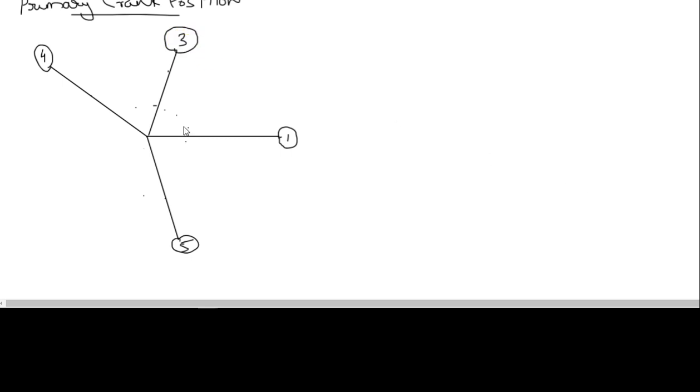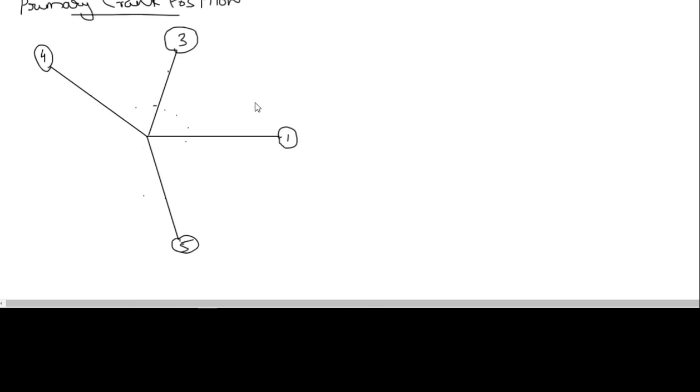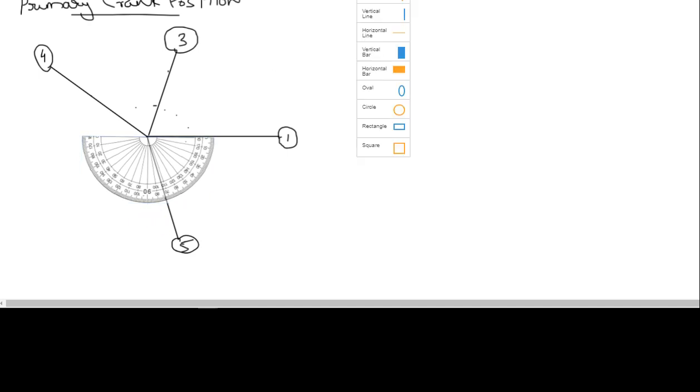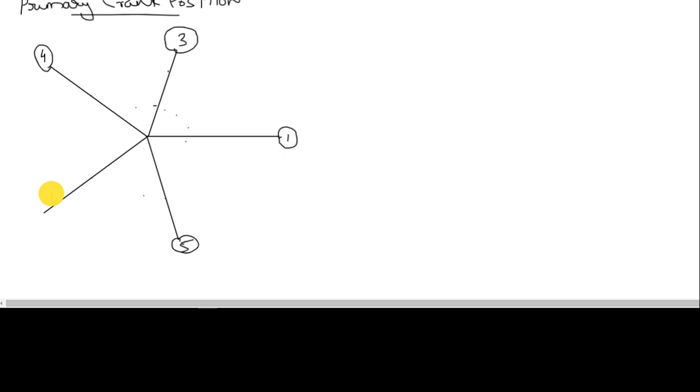That will be third one, and next one will be second one. Second one is at an angle 216 degrees. Actually it is 576. So 2 times 360 plus another 216. So 216 will be 180 plus 36. So already there is a 180. Take a 36 from horizontal, around here. Yeah. There is no scaling required to draw this diagram, but you should draw this diagram accurately so that we can trace the lines from this diagram easily to mark the second one.